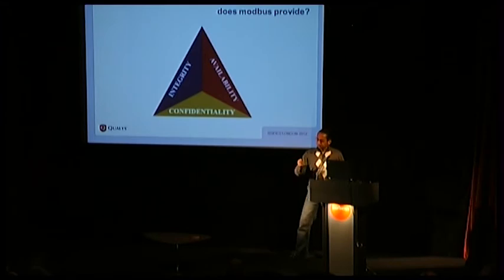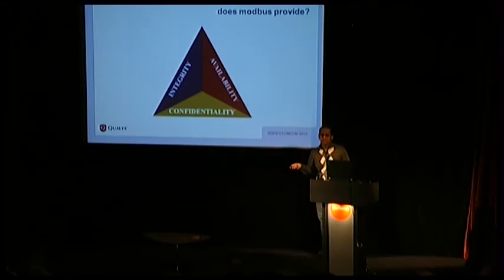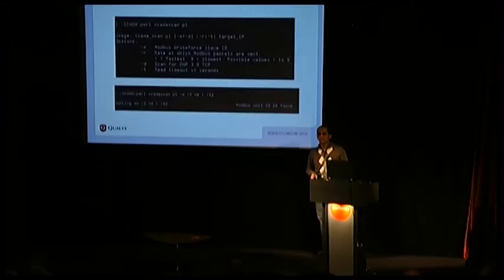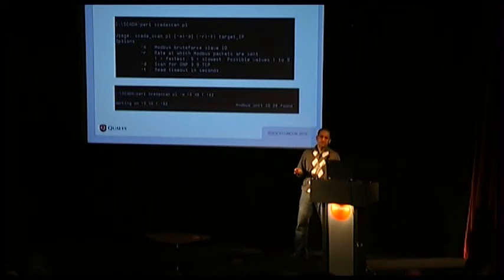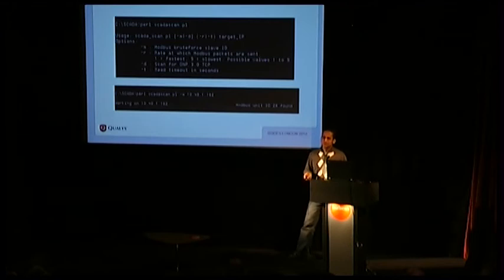But before going there, I want to show you a slide of this tool that I mentioned, which we are releasing. The name of the tool is SCADA Scan. In this screenshot, it is running in Modbus mode. It will scan for all your Modbus servers on the network, and it will also brute force all the slave IDs.